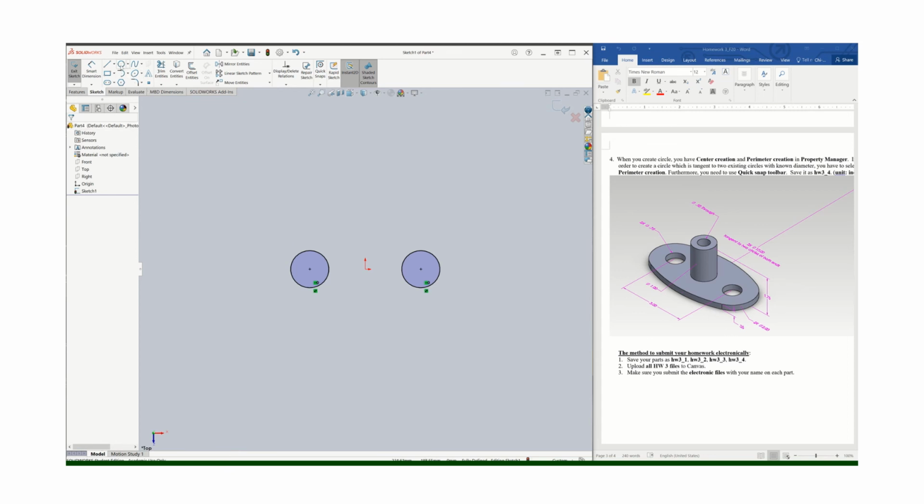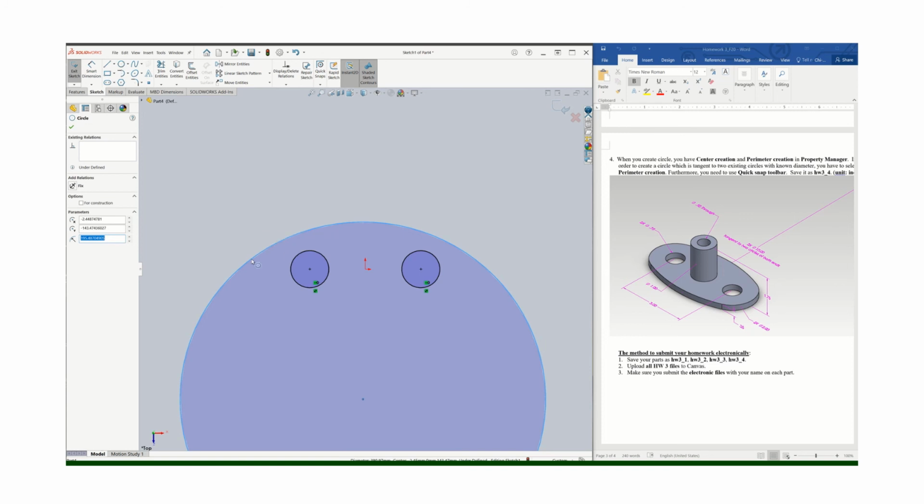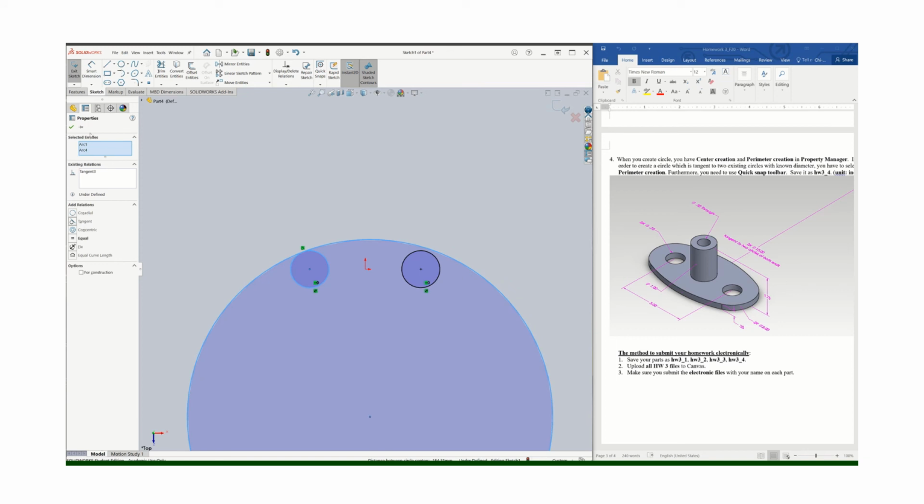I choose that circle right here. So that's the circle I have. Again, I already put the fix symbol here. Then I have this circle chosen, it's highlighted, Shift key, choose that small circle, and put tangency there. And that's the first constraint that I put.